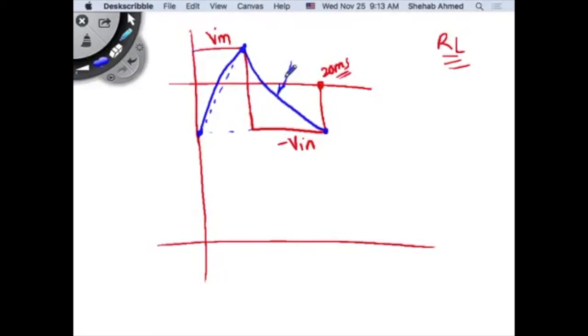No. They will have some harmonics that are in phase. So they may have the fundamental, they may have a third, they may have a fifth. But definitely, this square wave has significant transitions here. That means there's a lot more harmonic content in these fast transitions than in this slow transition. I don't have the Fourier series for this blue waveform, but since the waveforms are not identical, there's a difference between the harmonic content. That's the basics, just by looking at the waveform. If that's the case, I have some voltage harmonics that will not find a corresponding current harmonic at the same frequency, and hence will not be able to transfer real power.